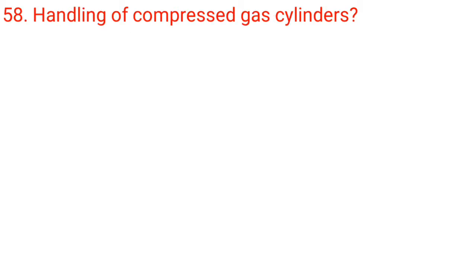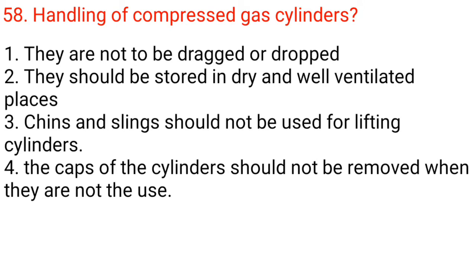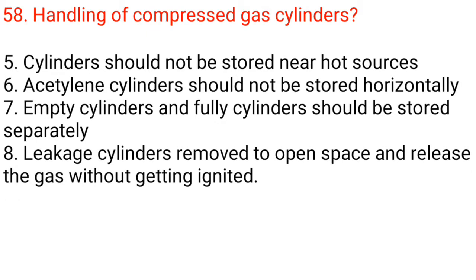58. Handling of compressed gas cylinders. 1. They are not to be dragged or dropped. 2. They should be stored in dry and well-ventilated places. 3. Chains and slings should not be used for lifting cylinders. 4. The caps of the cylinders should not be removed when they are not in use. 5.